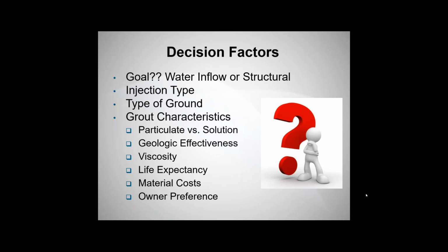And then you can get into the specifics, grout characteristics. So you've got your different grout types that'll be chosen, how long it needs to last. There's cost implications, and your familiarity with the grouting system itself. So there's a lot of things that come into it. Just like the slide I showed before, there's a million different parameters, but get the geology right, get the grout type right, and then you can start making reasonable decisions.